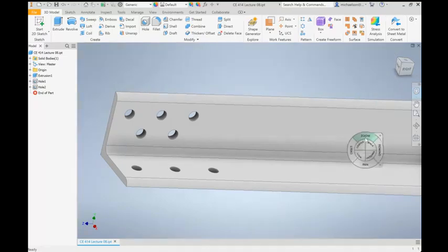So this is the gross section all the way out here, okay, and the net section is going to be somewhere in this vicinity. So the first thing you got to do is identify the lead line of bolts. The lead line of bolts are all of these bolts here, those 3, the ones that are closest to the gross section of the body. And then what you have to do is draw all of the possible failure paths that leave those bolts intact.